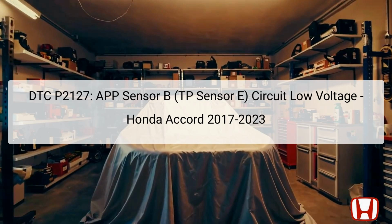The APP sensor's role is critical as it translates the position of the accelerator pedal into electrical signals that the PCM uses to adjust throttle opening for engine performance. Often, the APP sensor is located in the engine compartment, directly attached to the accelerator pedal mechanism. Addressing this DTC is essential for ensuring the vehicle responds accurately to driver inputs concerning throttle control.